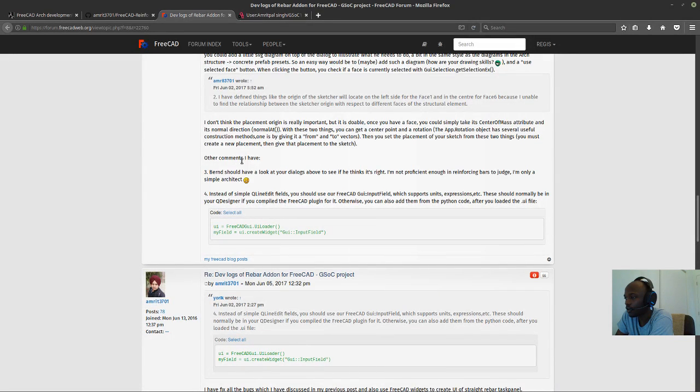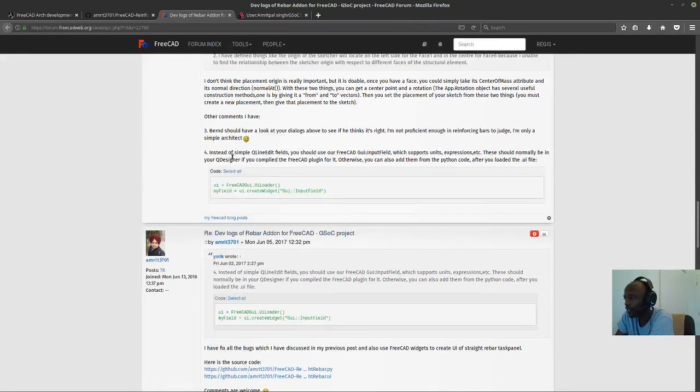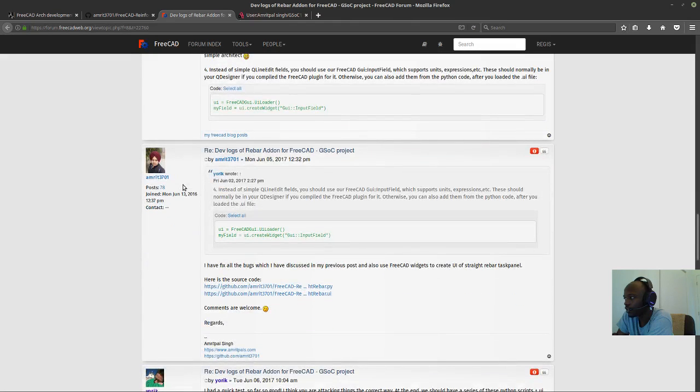Interesting. Other comments I have. Bernd should have a look at your dialogs above to see if he thinks it's right. I'm not proficient enough in reinforcing bars to judge. I'm only a simple architect. Instead of simple QLineEdit fields, you should use the FreeCAD GUI input fields, which support units, expressions, etc. This should normally be in your Qt Designer if you compile the FreeCAD plugin for it. Otherwise, you can also add them from the Python code after you loaded the user interface, the .ui file.